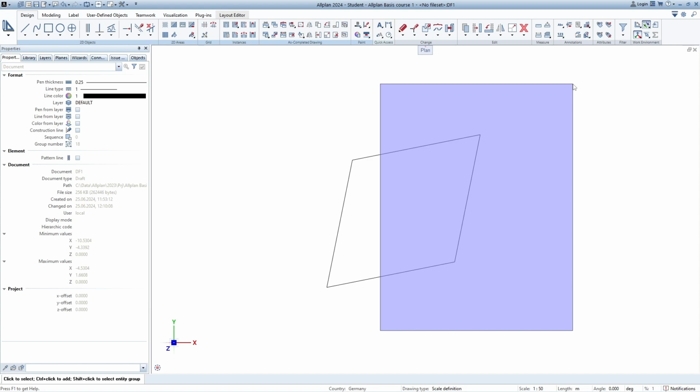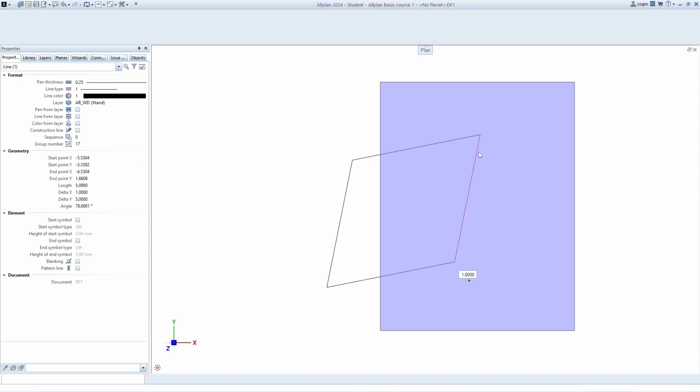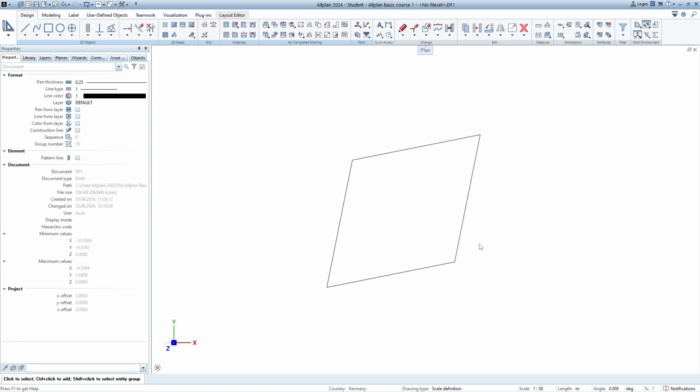So from the left to the right, I have the same marking as before, but now only the lines that are completely inside this field can become activated. And this is what I wanted to demonstrate to you. So if I go ahead, for example, with stretching entities, I mark this point, and take a quick look at stretch entities from points or enter dx.